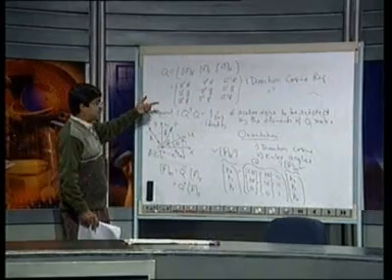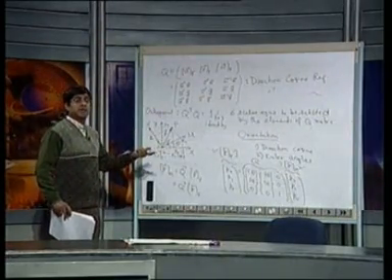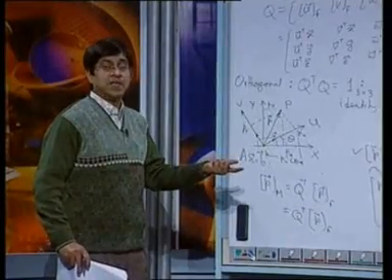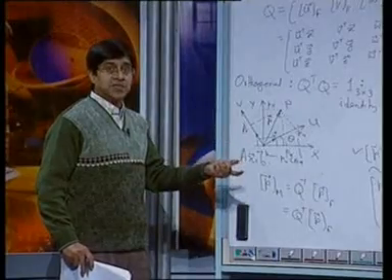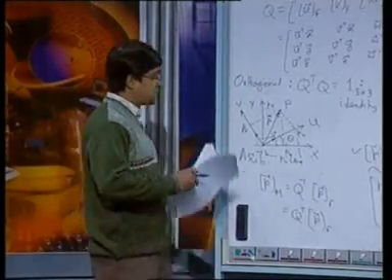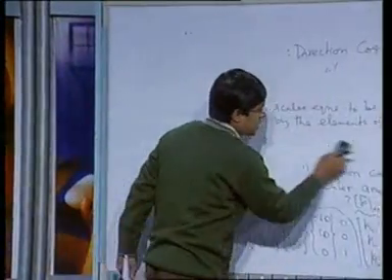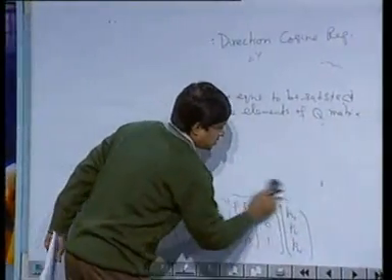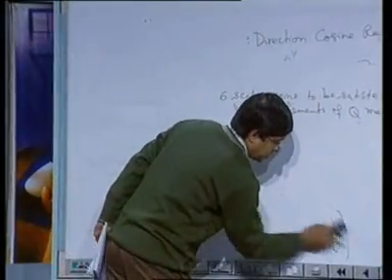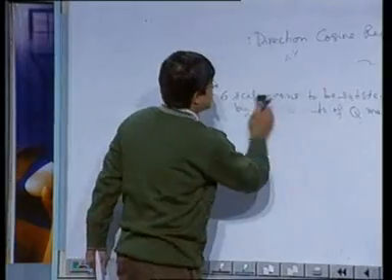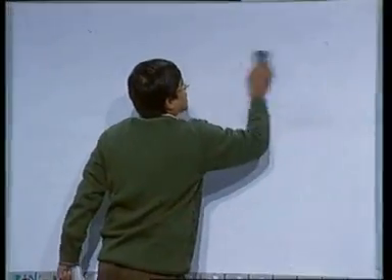So, when you go to the other representation, the Euler angle representation, we use that minimum requirement of 3, that means it has 3 degrees of freedom. So, 3 orientation parameters should be sufficient, and that is what we use in Euler angles. So, in Euler angles what we do is we consider the rotation with respect to x, y and z axis.